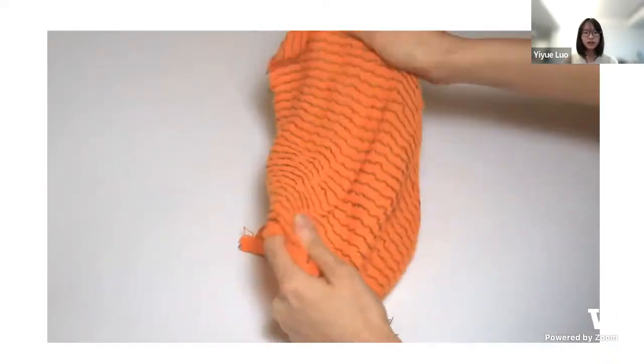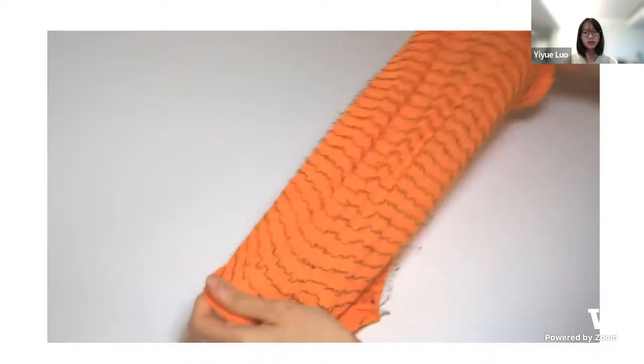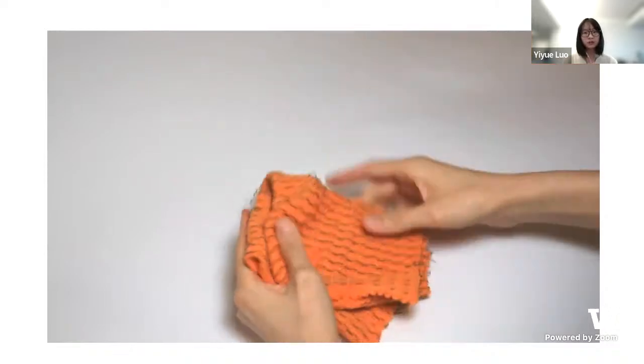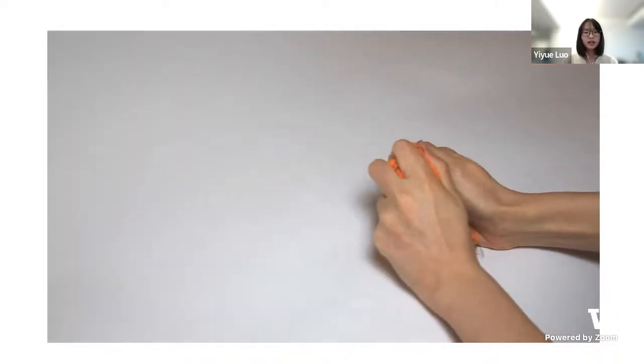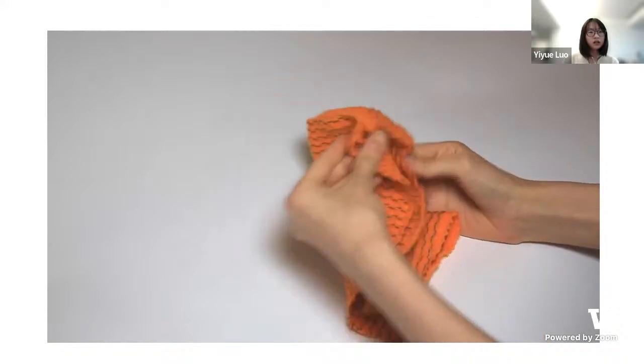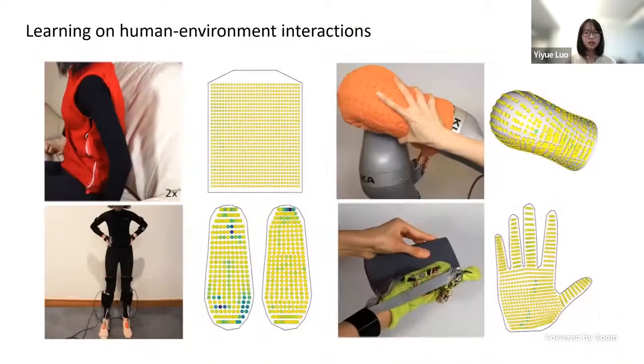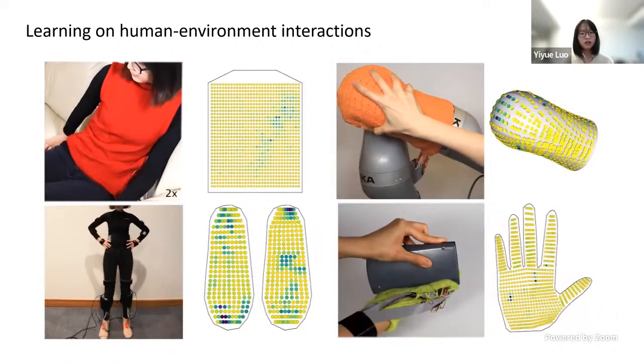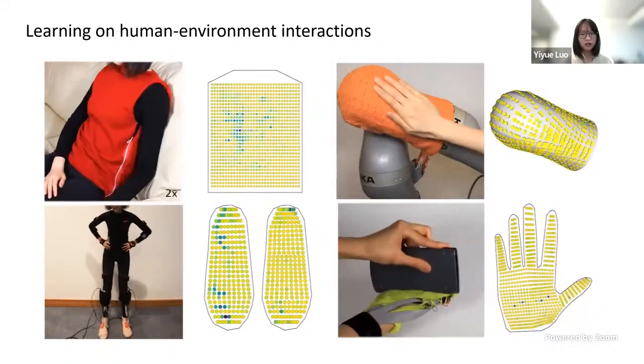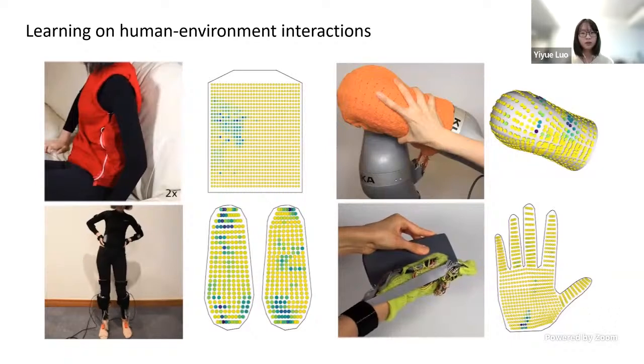The generated knitted fabric with integrated functional fiber is soft, flexible, and stretchable. And by generating and overlapping two pieces of fabric, one with horizontally integrated piezoresistive fiber and one with vertically integrated piezoresistive fiber, we can embed the pressure sensing matrix into fabrics and garments. So more specifically, we fabricated a full-size sensing vest, a pair of sensing socks, gloves, and a conformal robot arm sleeve.